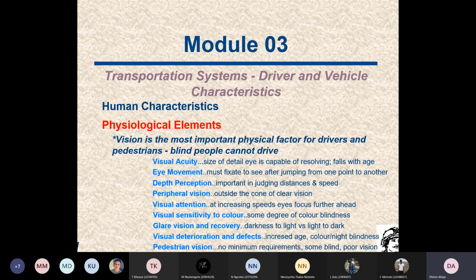Perhaps you may have done this in 2A, or I'm not sure if any of you covered it in 3B. Last semester, I gave you a little tutorial exercise and I said, draw three intersections, one road crossing another road. Simple sketch. At the first intersection, allocate your movement in both directions, so you have traffic moving in both directions. And then you plot your points of conflict: vehicles crossing over, vehicles turning left at the intersection, vehicles turning right at the intersection, where it conflicts with opposing, oncoming traffic. Plot your points of conflict.